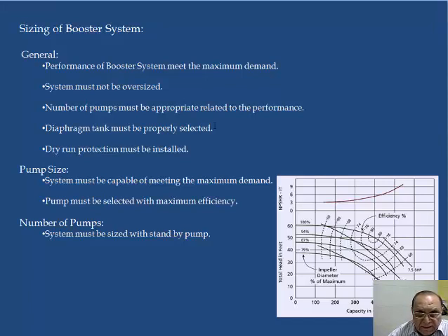It helps us in absorbing water hammer and reducing the running of the pumps for very small demands, which can be handled by the diaphragm tanks.